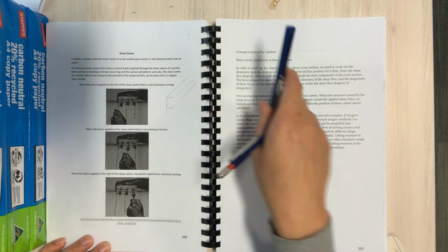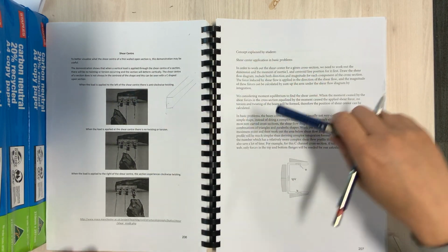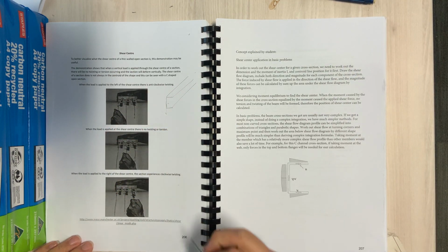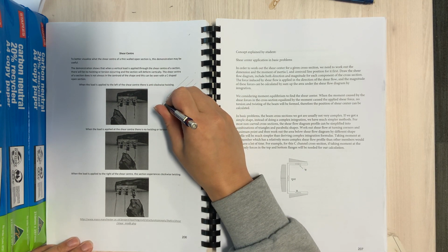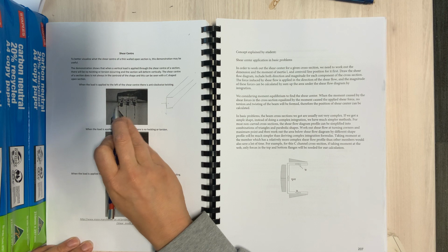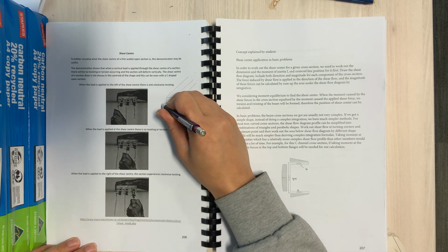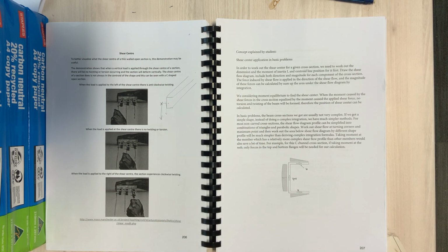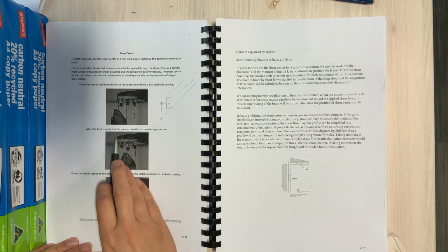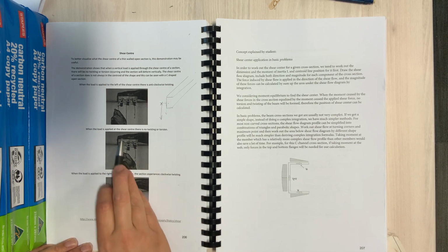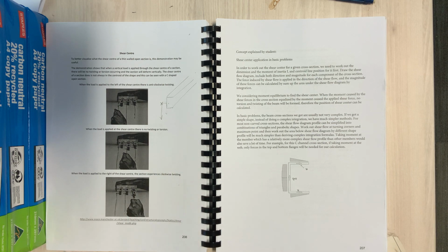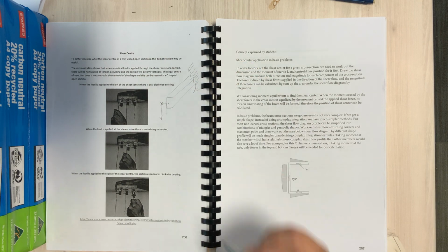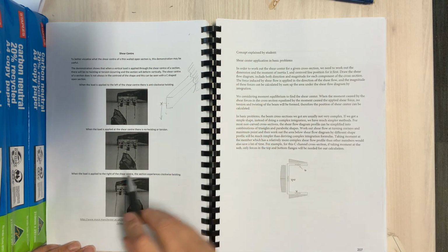This sort of experiment, where you're basically just pulling these things down, is quite useful, because you can see that if you attached a bracket there, and then you applied the load going down through the bracket, where the bracket goes through the shear center, you would see that when the load is applied at the shear center, there is no twisting or torsion of the section. At the back of this, all that would be built in. Okay, so we've got a built-in channel section.